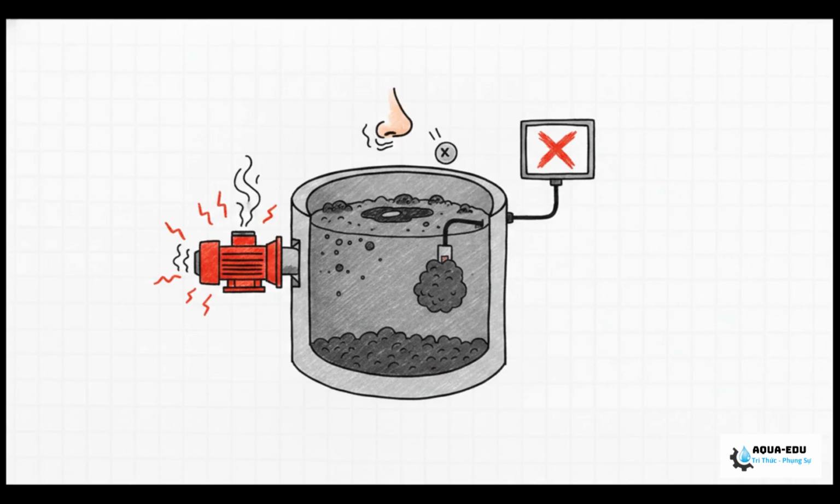Over in the aeration tanks, you'll see floating sludge and oily foam. Your DO and pH sensors will be coated in a sticky film, totally blinding your SCADA system. Your secondary clarifier sludge turns into this sticky gray-black mess. When you see this, brothers, you are in a fight.